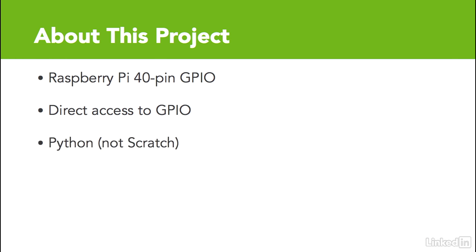Finally, the default Python GPIO library, rpi.gpio, doesn't include support for SPI. Instead, I'll use SPIDEV. Fortunately, this library is available in Python through a simple import statement. It is not available through Scratch.